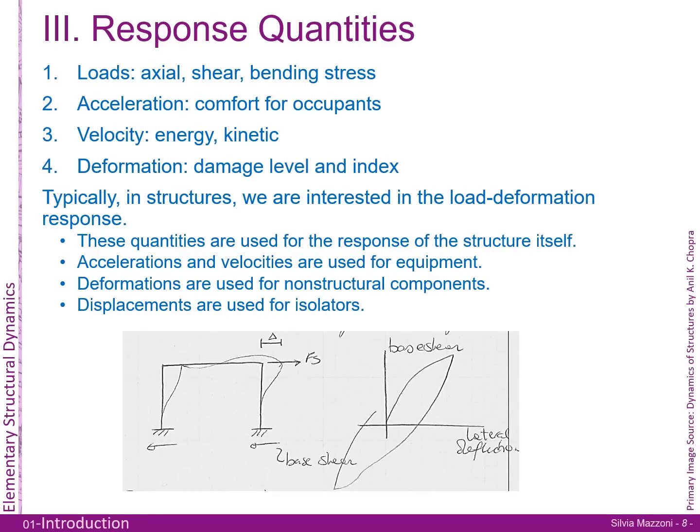You've got a system. What we're really interested in is what is the base shear as a function of lateral displacement. As we have an earthquake or even just some sort of loading, you've got a response that could be elastic or inelastic in your system. So some of the quantities that I described above are really used for the response of the structure itself. The accelerations and velocities are for the equipment. And importantly, deformations are also used for non-structural components, such as partition walls, such as glass.